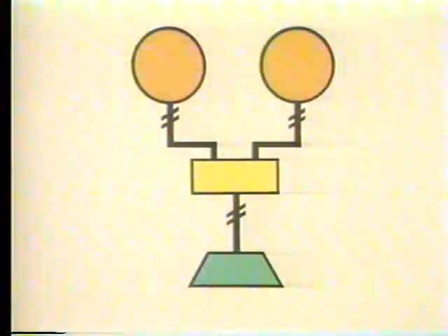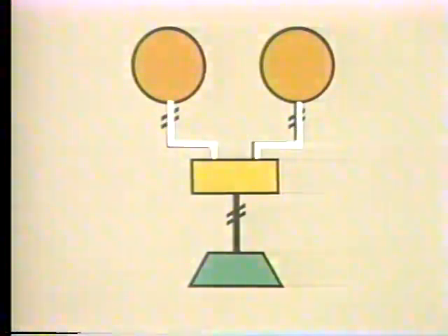In this system are two measuring elements, a controlling element and a final control element. Each of the measuring elements monitors a different process variable, and each provides a separate input signal to the controlling element. These signals represent the values of the monitored variables.